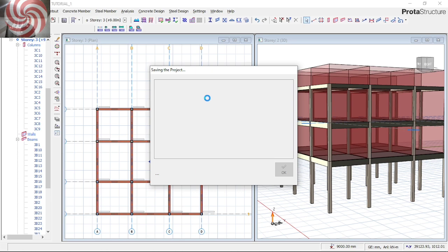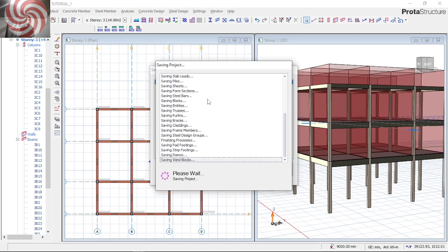After that, you come to select your stories. After selecting stories, how many stories you want to use. If you want to use a 3-story building, you put 4 because of the roof beam. Then you generate them. After generating, you come and place your beam wall loads.